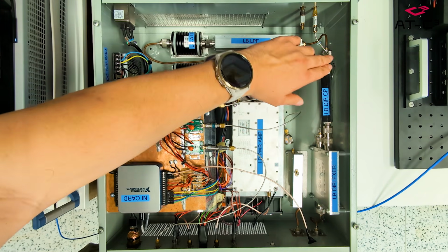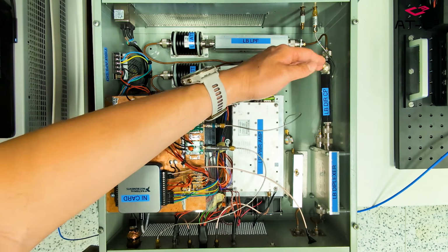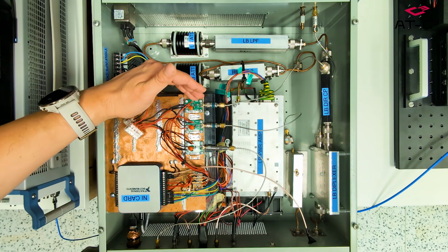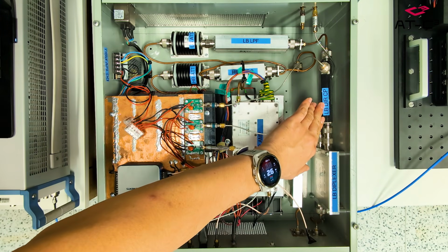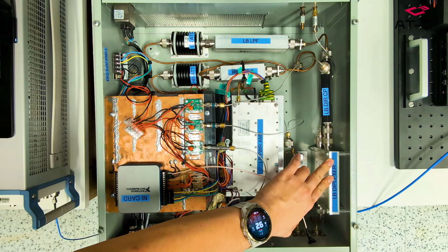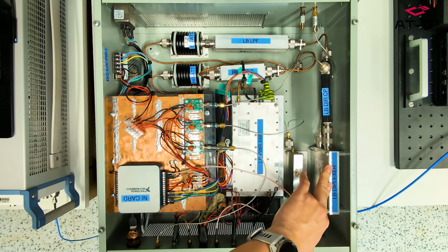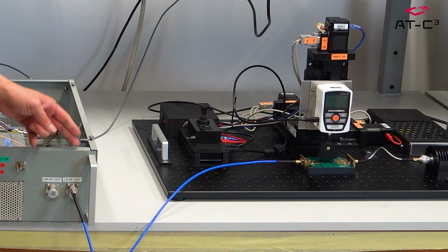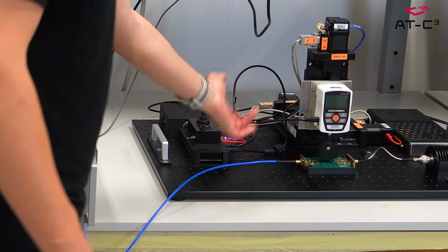And then it goes into the directional coupler. This directional coupler helps us monitor the forward power with another log detector. Then the forward fundamental signal will go into the duplexer. This duplexer will reduce the self-harmonic even further. And from the common port, it sends out the clean signal to our test fixture.